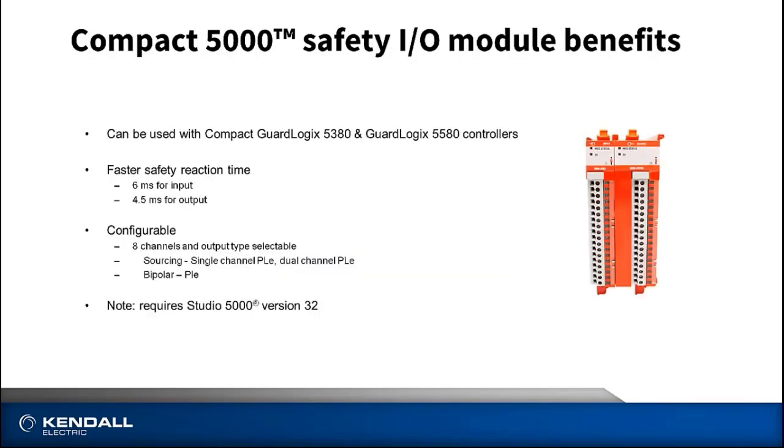Taking a little bit closer look at these new safety modules, keep in mind again, these are compatible with the 5380 Compact GuardLogix and the 5580 GuardLogix controllers. At this time, the Compact 5000 I/O structure is not compatible with any other PLCs.